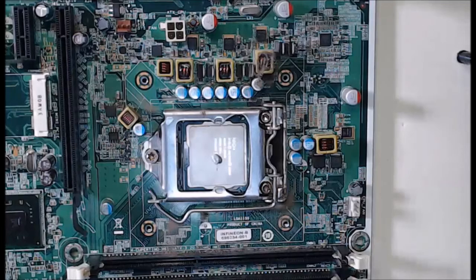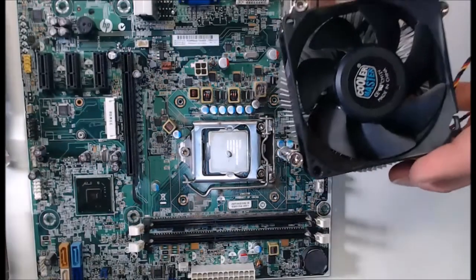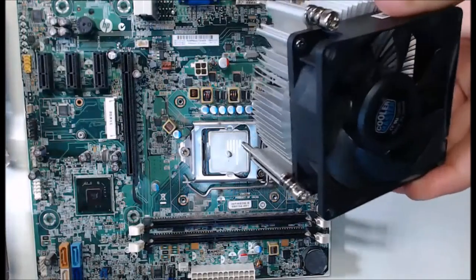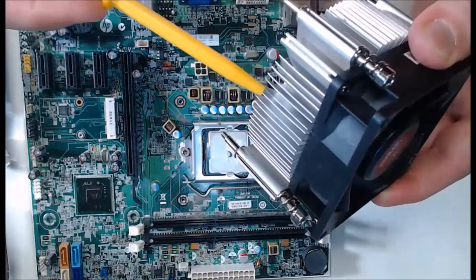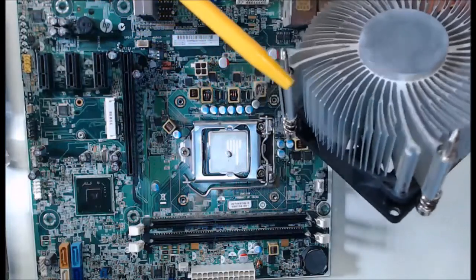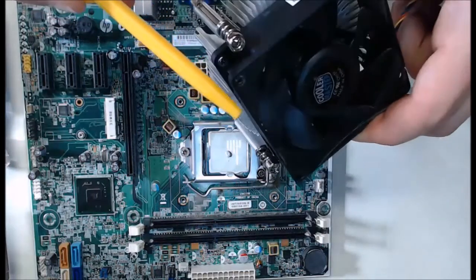These commonly have a fan attached to them, but not all of them do. These fins we see here are going to absorb the heat from the CPU and have slots for airflow to move in between. The fan on top of the heatsink will help draw the heat away and cool the fins. This will allow them to absorb more heat from the CPU.